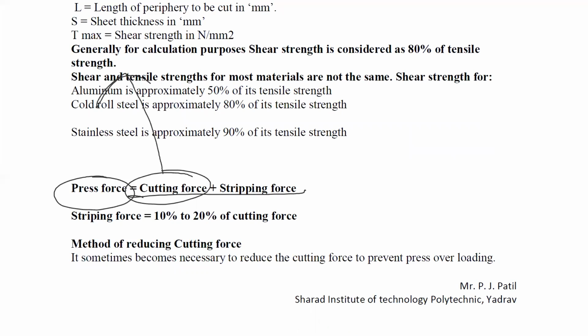Stripping force is the force required to hold the stock material in its position. That means when you hold the workpiece or the stock material in its position while cutting, the force required for that is the stripping force, and it is generally 20% of the cutting force.